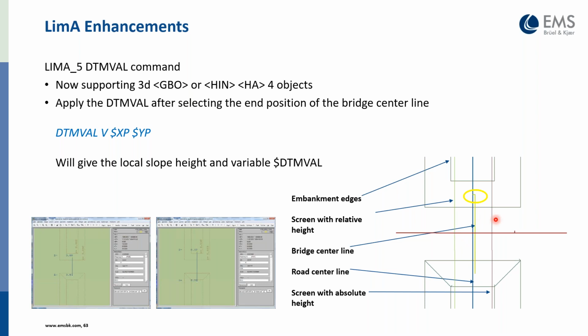And you've got a couple of barriers on the edges of the bridge, which has a defined width, and which have either relative or absolute height. The trick is to be able to get this bridge to align with the embankments so that you get a smooth road, so your road doesn't all of a sudden have a step in it. And either through importing data or through creating, you may get a bridge item like this, which is modeled relative to the terrain below it.